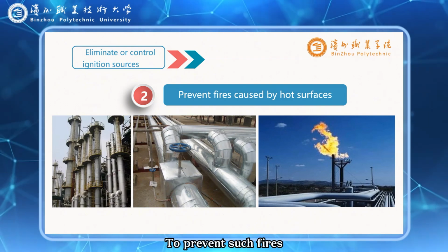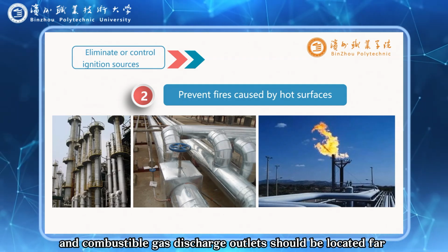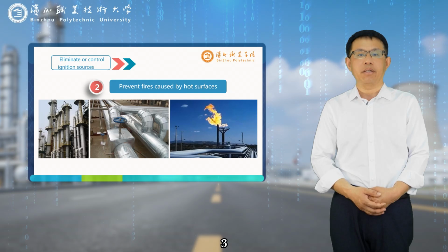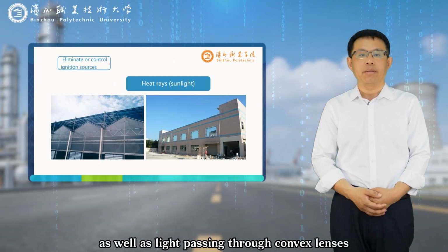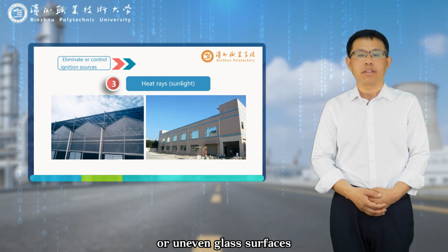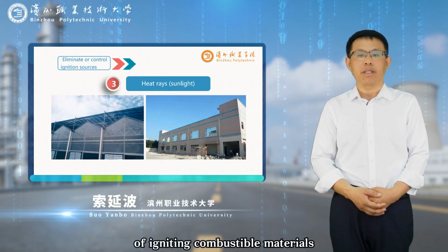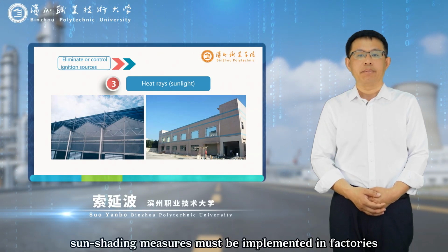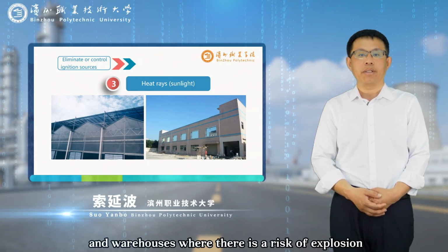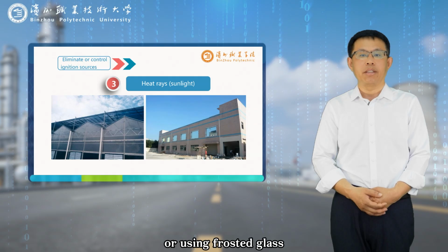To prevent such fires, high-temperature surfaces should be insulated or thermally shielded, and combustible gas discharge outlets should be located far from high-temperature surfaces. Third, thermal radiation, direct sunlight, as well as light passing through convex lenses, curved glass with bubbles, or uneven glass surfaces can be focused to create high-temperature hotspots capable of igniting combustible materials. Therefore, sun shading measures must be implemented in factories and warehouses where there is a risk of explosion. Examples include painting window and door glass white or using frosted glass.